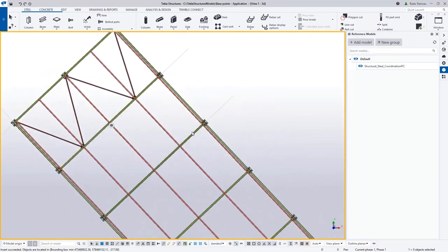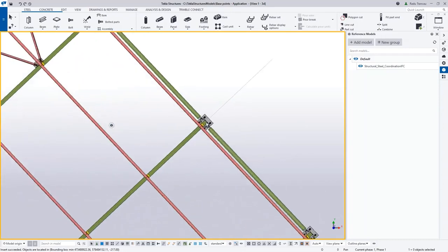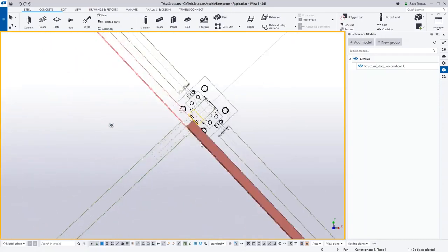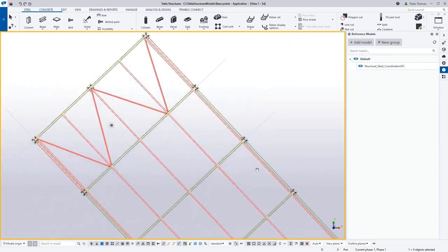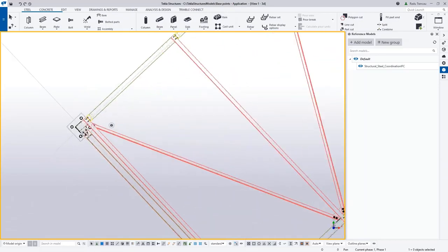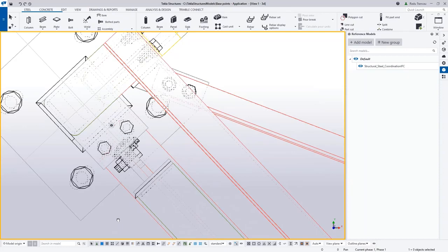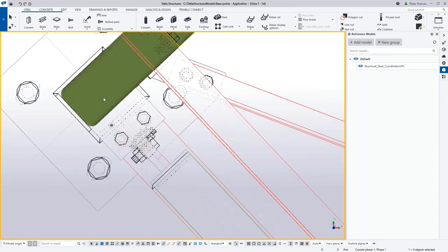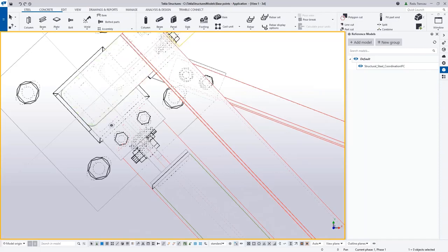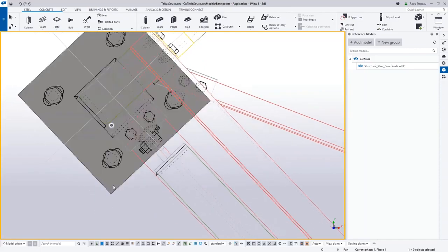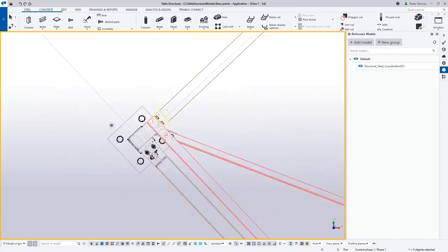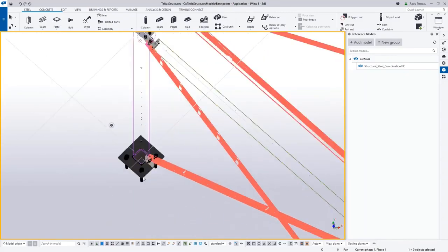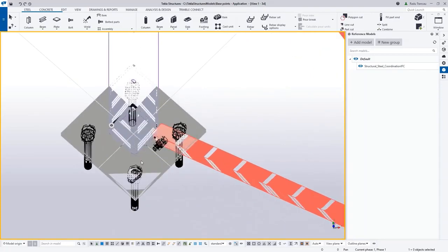We know from my PDF previously that this point here, intersection C2, will need to sit in the origin, but obviously you might not know that, so you just want this point here, or as close as possible, to sit in the model origin. So the goal is to bring this IFC closer to the Tekla model origin. As we saw previously, you can't really snap on this point because we're too far away, and the accuracy makes the situation not work very well.